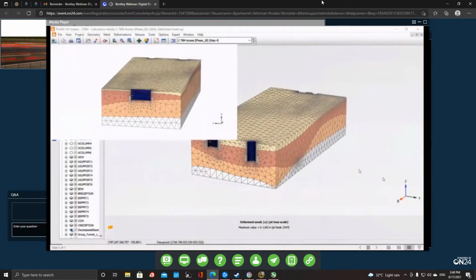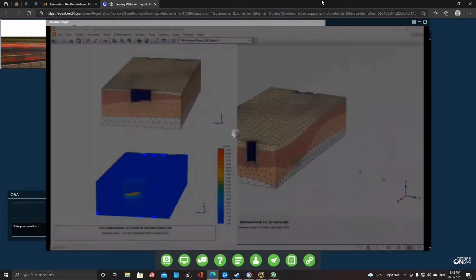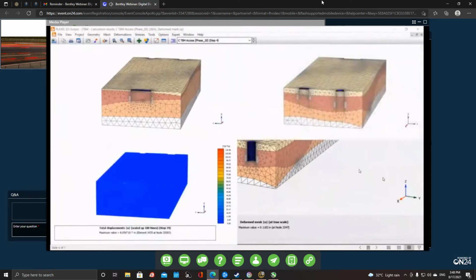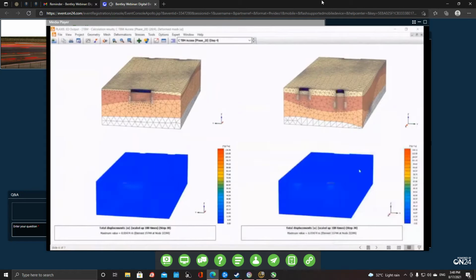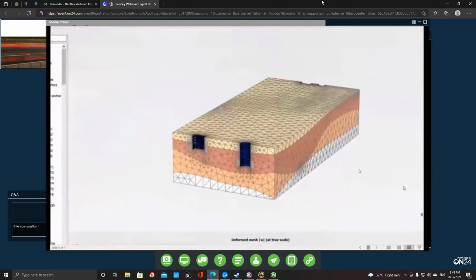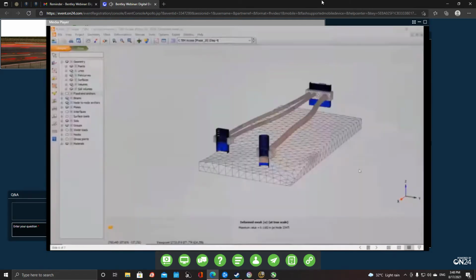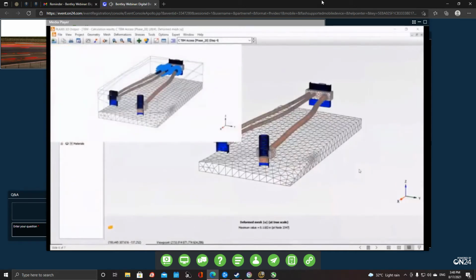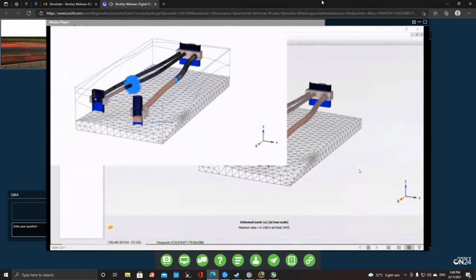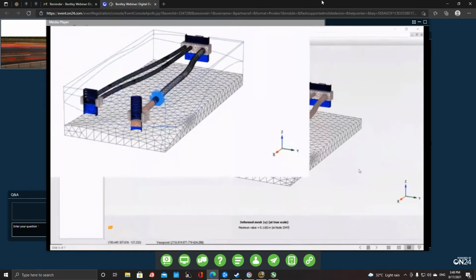Mechanized tunnel construction, or the TBM method, just to sound a bit commonplace, involves a customized tunnel shield, mostly circular if not rectangular, adapting to the desired dimension of the tunnel to be constructed. It is equipped with a cutter head or gripper at the bore front, depending on the ground condition, as well as excavation and slurry regulating chambers depending on the type of the shield. The idea is to maintain a sufficient face pressure during advancement, thus to control the ground movement.